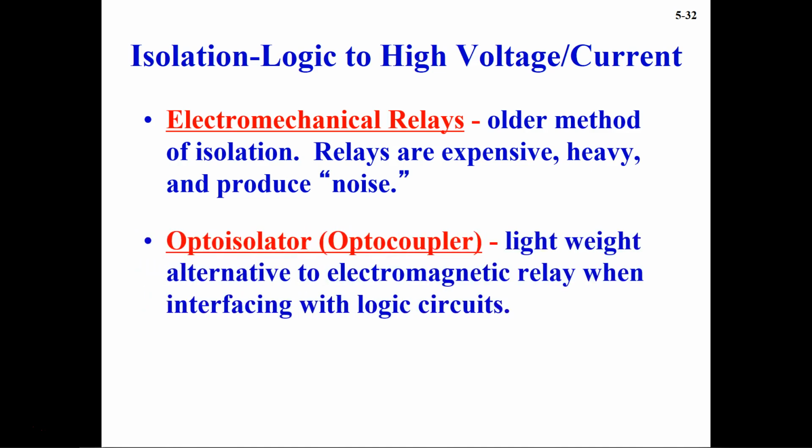And then we have this opto-isolator, also called an optocoupler. It is lightweight and it is an alternative to an electromagnetic relay when interfacing with logic circuits. So these are the more modern type. If you see the traditional type relays, they have several mechanical failure modes associated with moving parts. So these are the solid state relays, and this is one of the solid state relays which offer several advantages in performance and in terms of design also.